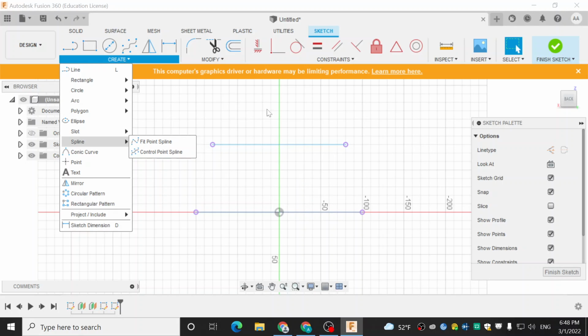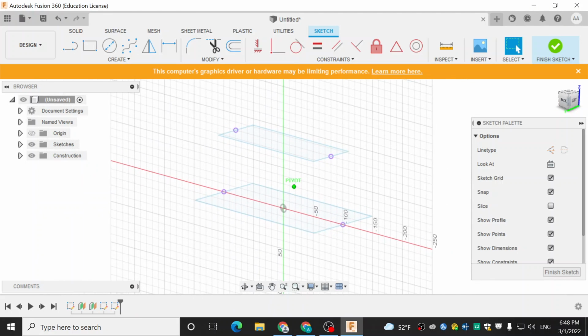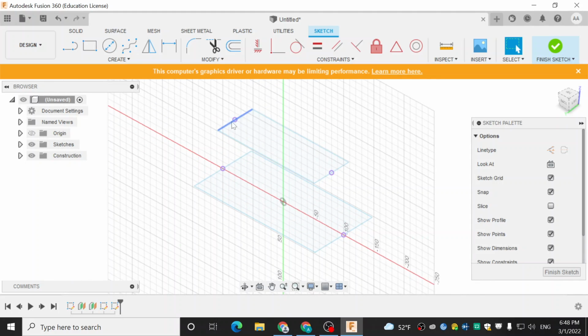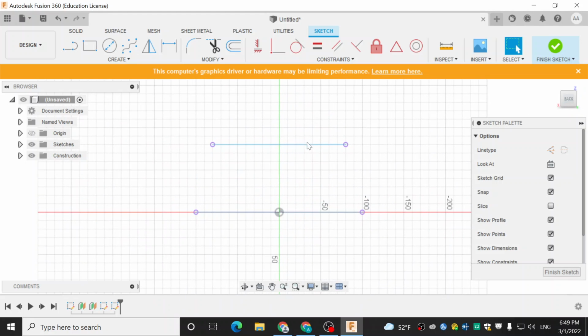So just to go over that, the Project tool took the geometry from another perspective that we had previously made, and it projected it in 2D form on our current sketch plane. So here we selected four edges, but in the 2D perspective that we have, this is just a line. Those edges show up as points because they are perpendicular to our viewpoint, so they're coming in and out of the page. So you don't see them as edges, but you see them as individual points, which will be important for us because then we'll be able to snap our lines to those points, if that makes sense.